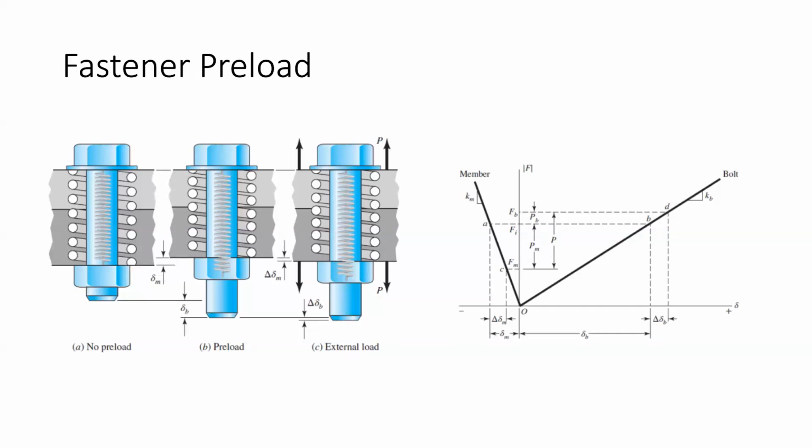So the most important way of retaining a fastener is the preload. And there's a couple other things you can do, like Loctite, if you guys have ever heard of that. But it's not a fix-all solution, right? In general, you need to retain your fastener by hitting some amount of preload. And if you're not tightening it properly, the fastener can also just back out, which is a really important consideration.